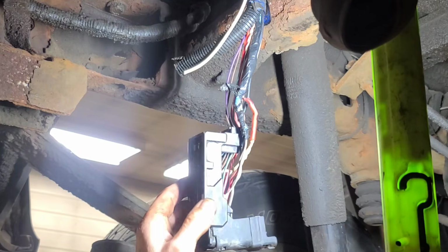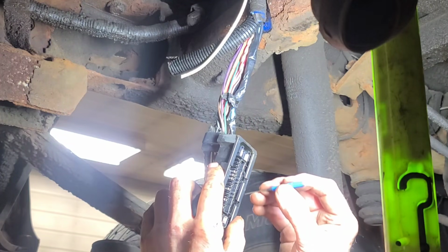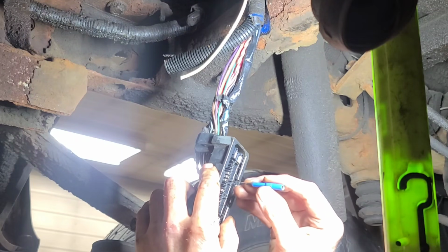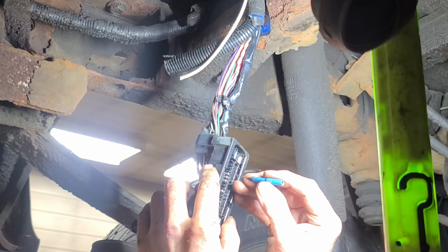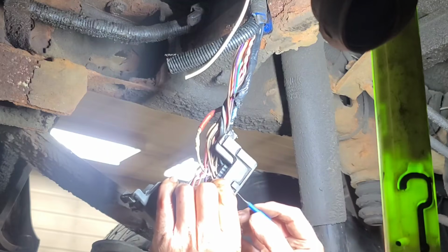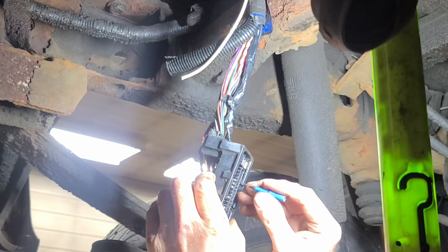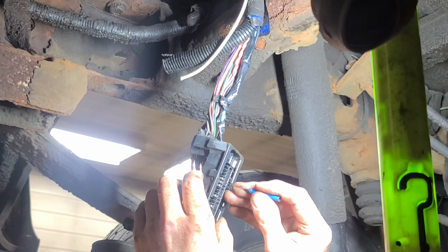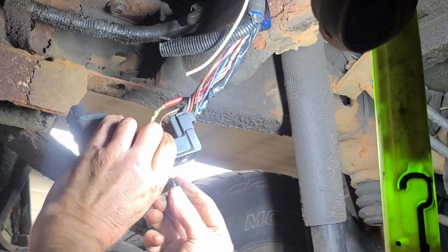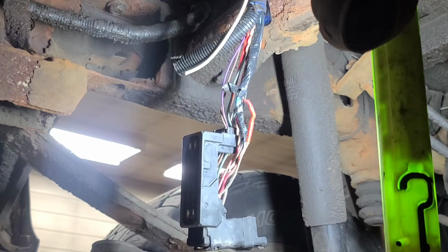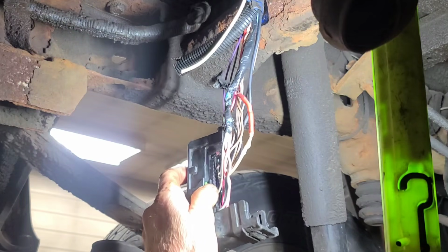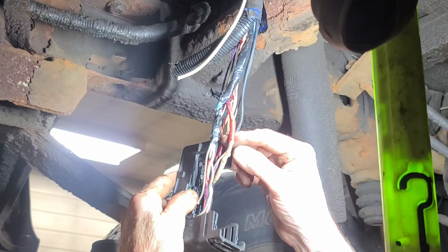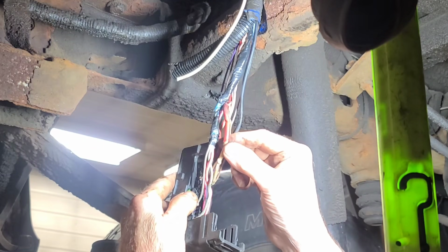Or do we have an open in the harness somewhere else? No grip, no grip. Some grip. Oh, that's a gray wire, so that's not a CAN bus wire. So these are the other CAN bus, no grip. Look. So those 4 wires are compromised as well. But they've been repaired. One has been repaired.